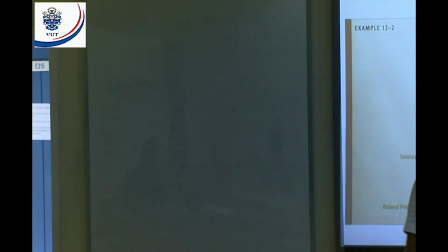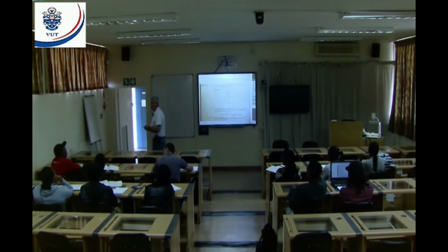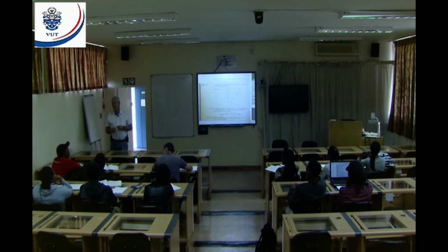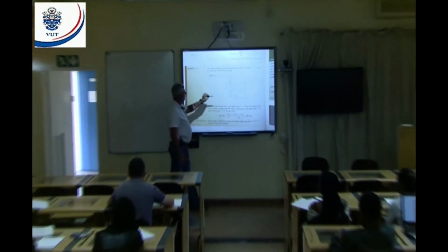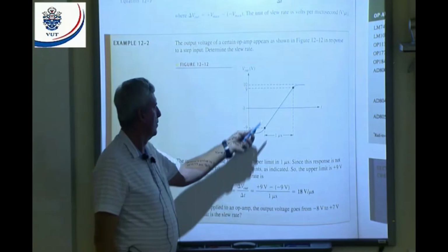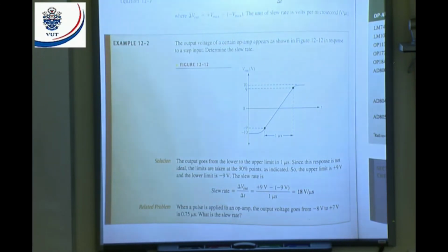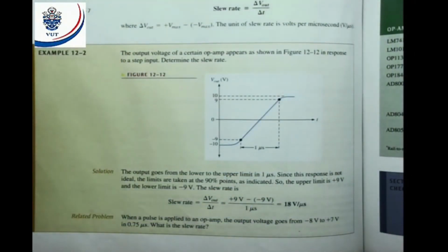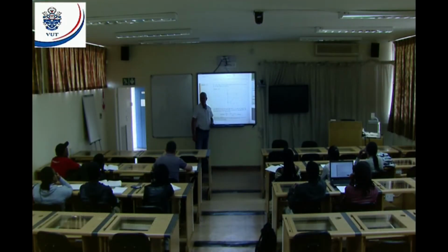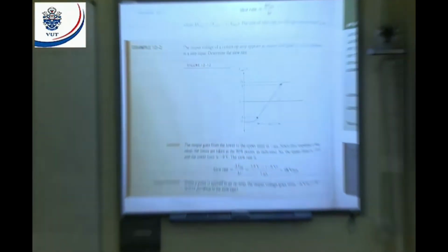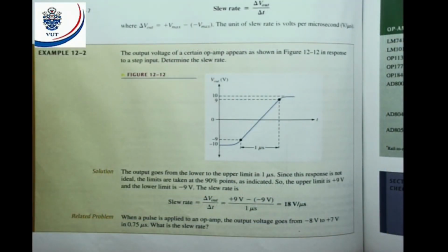Yeah. So, meaning it will always be 10%? It doesn't depend on the rise time? It has to be a straight line. Yeah, you see, you normally get something like that. It's normally not straight like that, you understand? And that's why they go 10% up and 10% down, to get on that straight slope. Because how do you determine that position there? That's why they normally go 10% and 10%, from the top 10% down and from the bottom 10% up. Or let's say from 10% to 90%. That's a standard.